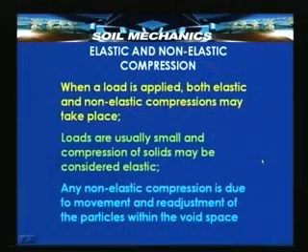The elastic part of the compression is primarily due to the compression of the solids, and these are going to be very small because the solids are virtually incompressible, and we never would like to subject the solid grains of the soil to such excessive loads as to crush them, because we want safety of our foundation and the structure which is supported. We would therefore never like to subject the solid particles of the soil to such heavy loads as to break them or crush them or make them disintegrate. Therefore, all the loads will be well within limits.